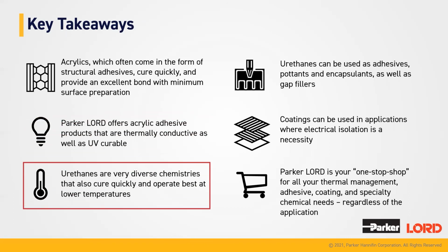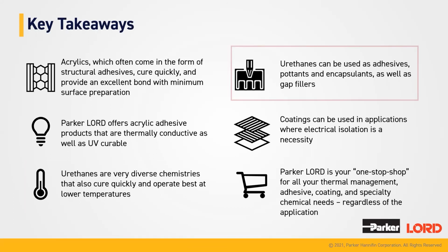Urethanes are very, very diverse chemistries, but they also cure quickly and operate best at the lower temperature range. Urethanes can be used as adhesives, pottants, and encapsulants, as well as gap fillers. Those gap fillers are a replacement for the traditional incumbent product, which are gap pads.